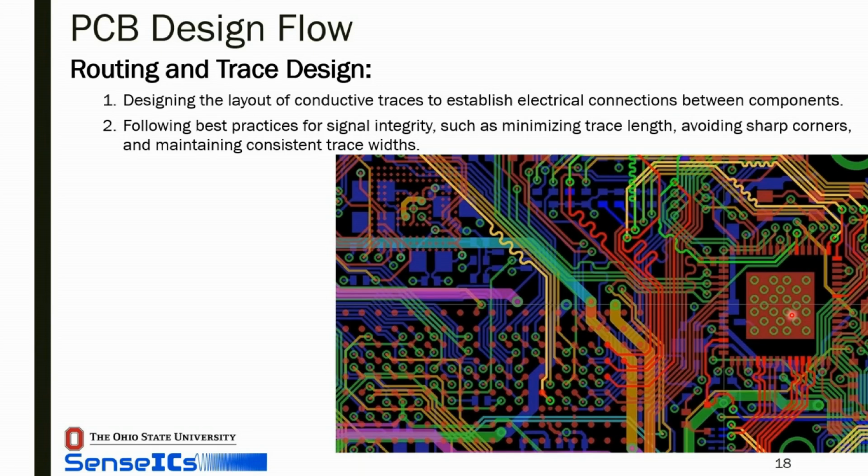Go ahead. People online are just saying whenever you get a response from the audience, they'd like to hear it. So we had a response on length matching, which was correct. That's for the squiggly lines. We had responses on these vias here, which I did not design this board, but I think they're probably used to remove heat from the component that will eventually be mounted there.